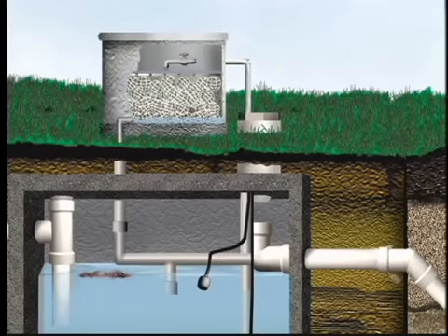The quality of the effluent depends on the media size and how the water moves through the system. A film of biological growth on the media feeds on the contaminants contained in the wastewater. As the film grows, it will exceed its ability to hold on to the media. Pieces of the biological growth will break off and fall back into the tank with the wastewater for decomposition. Wastewater flows from the recirculation tank into the land application system.